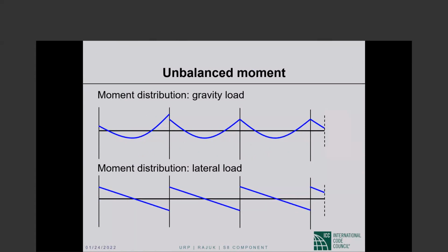The blue lines indicate the bending moment diagram. At the exterior support, this entire slab end moment must be transferred to the column for equilibrium.